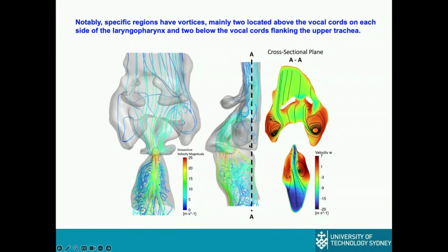So this way you can see how these vortices happen. The turbulence actually happened for this lower Reynolds number. I have to check. I think we used about 7 million mesh for here. But we have to run it for a longer time because it's time dependent. It's not a steady state. Okay, it's a transient.